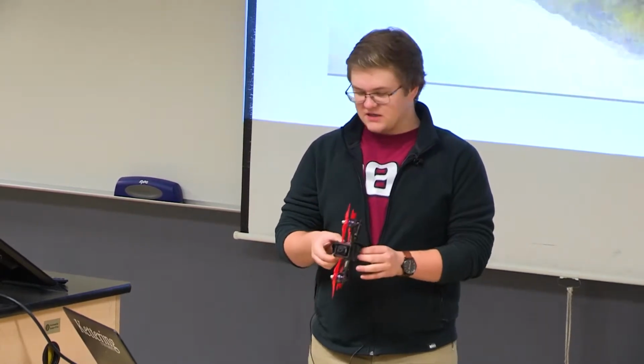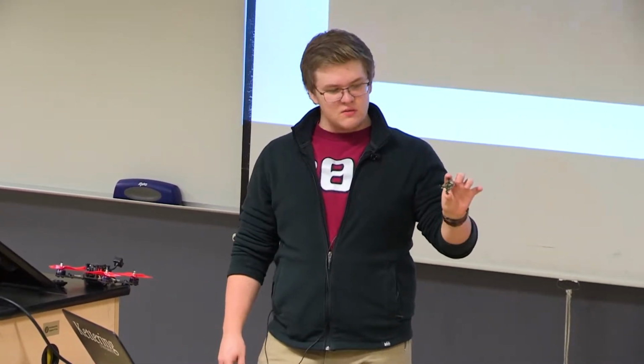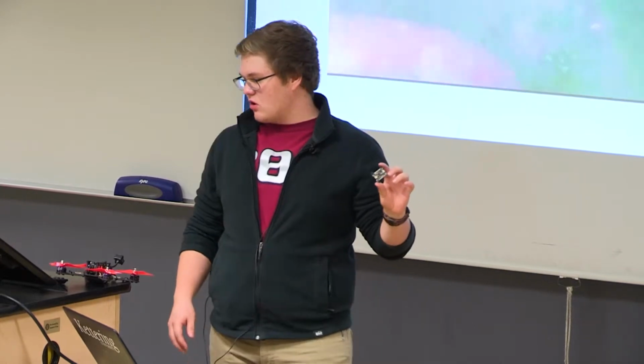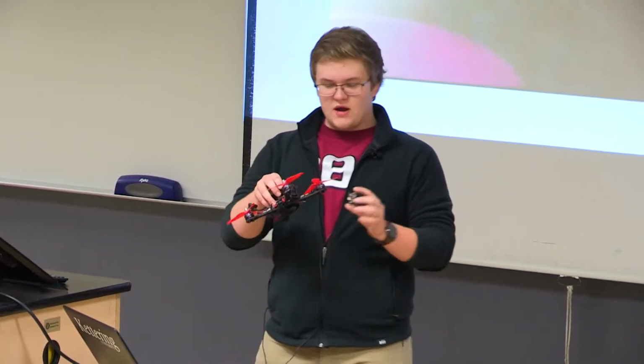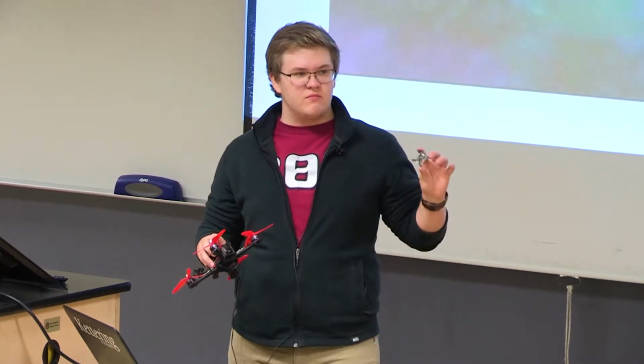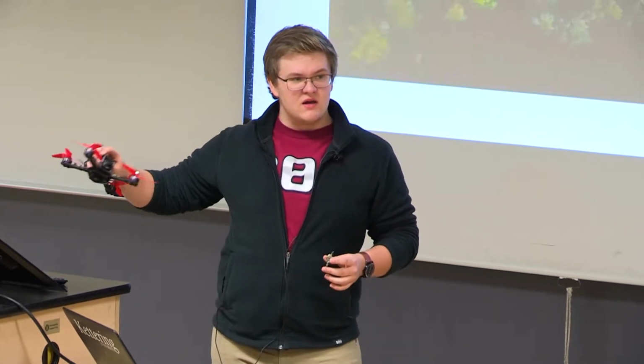It's a PID controller, and that runs on this tiny little board. On this board, there are 3 gyros and 3 accelerometers, and a processor running a PID controller. That allows this quadcopter to take feedback from the gyroscopic and accelerometer inputs and be able to fly.